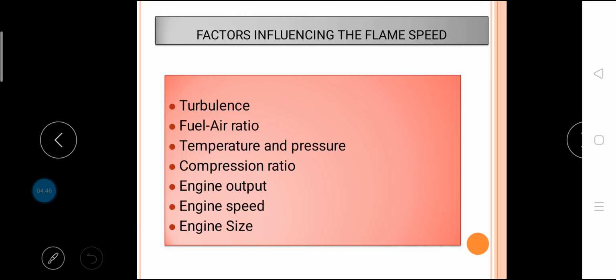The main disadvantages of spark ignition engines are the poor combustion at low speeds and the necessity of mixture enrichment, that is, equivalence ratio between 1.2 to 1.3, which causes wastage of fuel and discharge of unburned hydrocarbons and the products of incomplete combustion like carbon monoxide, etc., in the atmosphere.